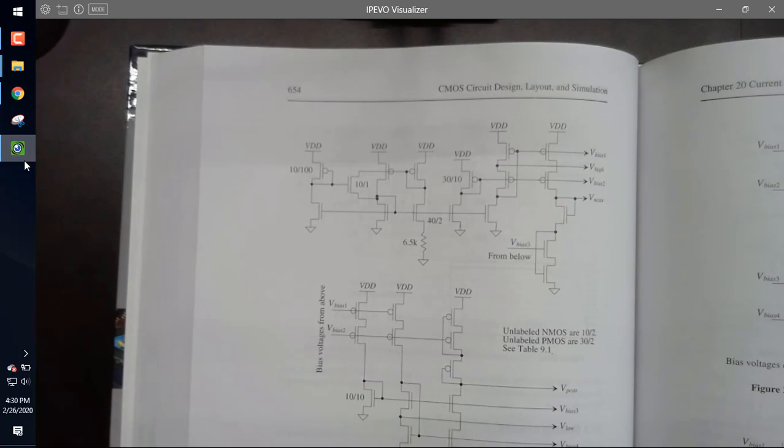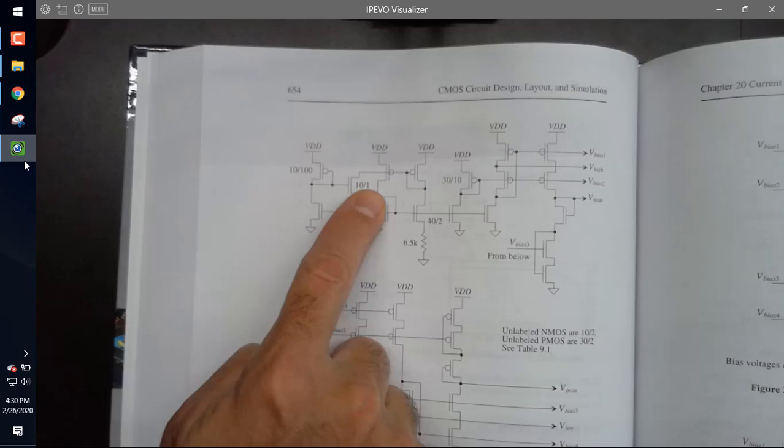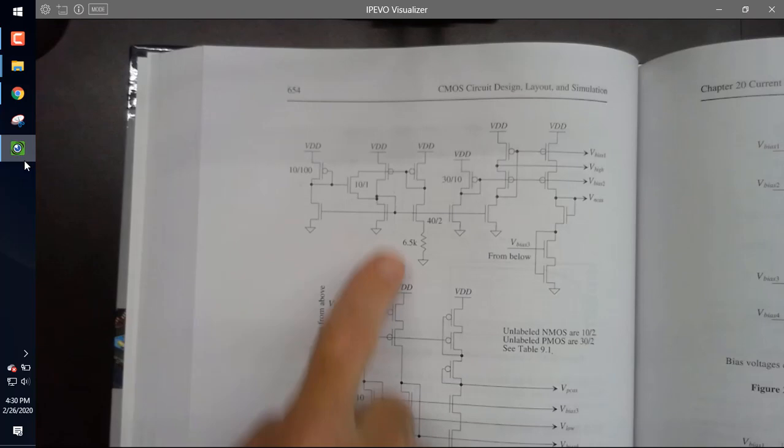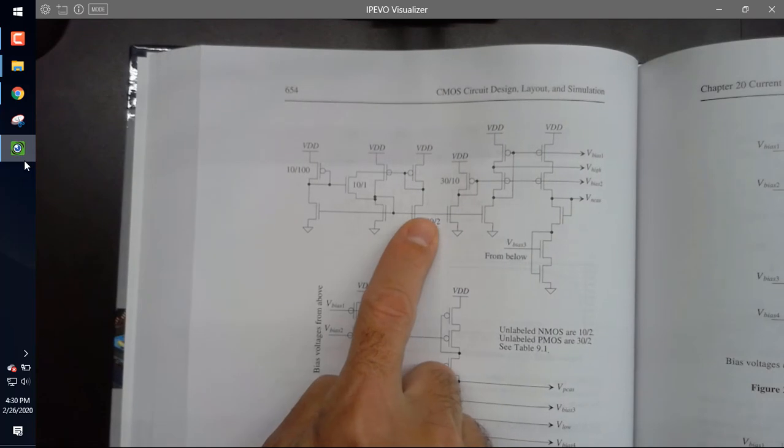You know, here's why I'm going over this. If I was a student and somebody threw this circuit at me, I'd be like, holy crap, what the hell is that? All right, and I want to dissect it. So what is the point of the beta multiplier? Why do we even put this in our circuit? Current that's independent of VDD. All right, everybody got that? So VDD changes, the current stays fixed.